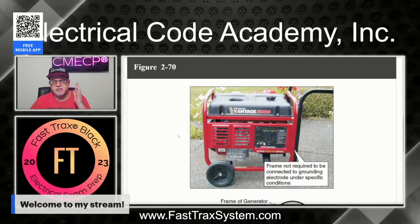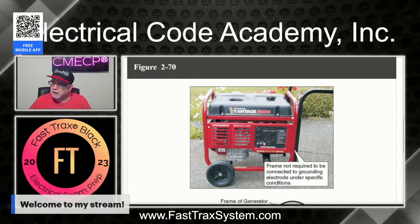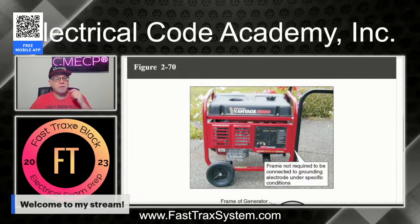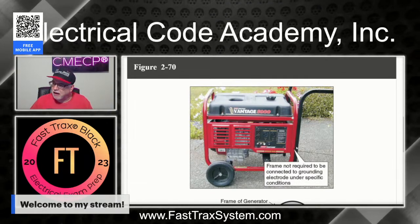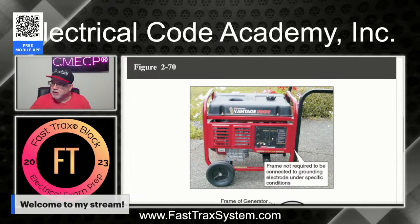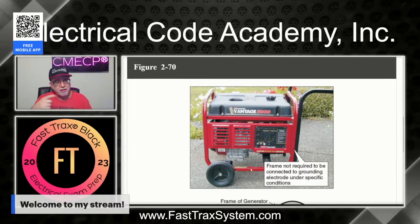So here's a generator, a very standard generator. This is a 5,000 watt generator. You notice here's the metal frame. You notice it's on non-metallic wheels, plastic wheels, so it is not in contact with the earth. Now, this frame is not required to be connected to an electrode under the specific conditions that we just read. Obviously here are the receptacles that are built into the generator. That meets one of the components. The other aspect of not having to have the electrodes is that it has to have the connection from the neutral point and from the equipment grounding terminal connections on these receptacles over to the frame. All of that has to take place.